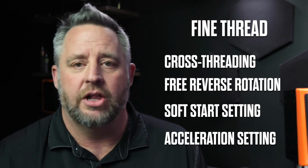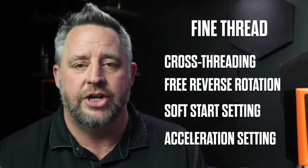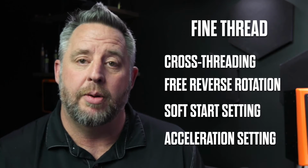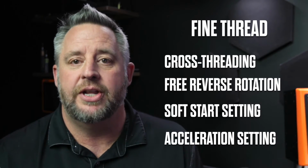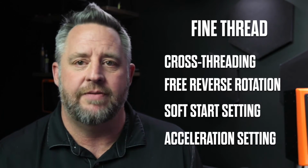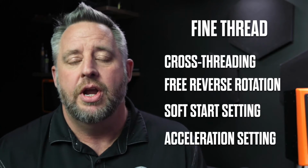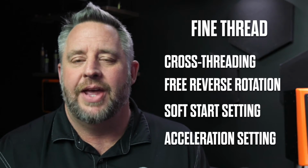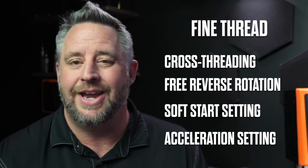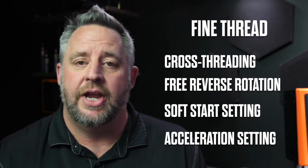So if we are doing a clockwise tightening, we can turn the fastener in the reverse rotation at an adjustable, or programmable, RPM of our choosing, but typically that's going to be a very slow RPM, and we're only going to turn it for about 7/10 of a turn in our example here. That allows the first thread to kind of drop into the assembly, and then we can reverse to the tightening direction.